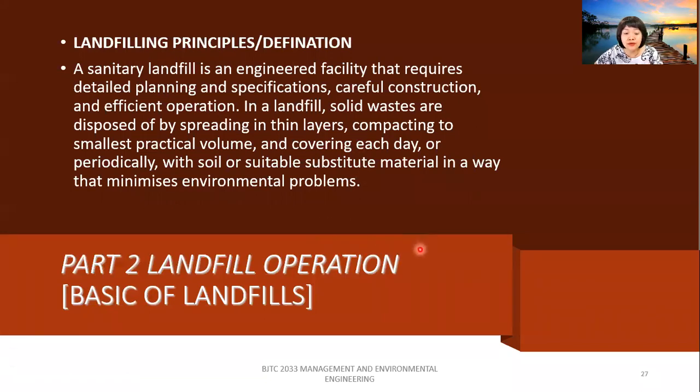Okay. So the landfill operations, this is for sanitary landfills. When we talk about operations, we go into sanitary landfills. A sanitary landfill is an engineered facility that requires detailed planning and specifications. So it needs careful construction and efficient operation. In a landfill, the solid waste is disposed of by spreading in thin layers, compacting to the smallest practical volume, and covering each day or periodically with soil or suitable material in a way that minimizes environmental problems.